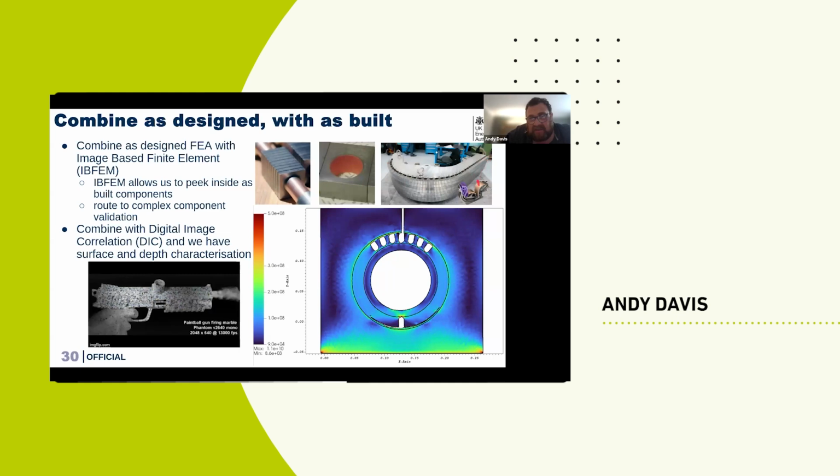So these stripes you're seeing are all these stripes on that component there. When these things are made, they're made through welding and brazing and various heat treatments, and the exact way that this material is bonded together impacts its thermal and mechanical performance. So we can take many X-rays of these systems, figure out exactly where the adhesion hasn't happened, there's been separation and cleavage, and then we can see and understand in simulation terms how that will impact the performance of that component. Critically, we can take technologies like digital image correlation.